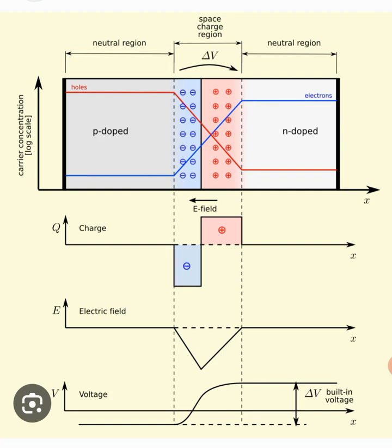Now let's define some electrical quantities, such as charge with respect to the x-axis, and see their profile. The electric charge, as you can see here, in the depletion region, in the blue zone where the negative ions are shown, is maximum right over here, and at the junction it is 0, and again in the depletion region where positive ions are present, as indicated by the red dots, the charge is again maximum.